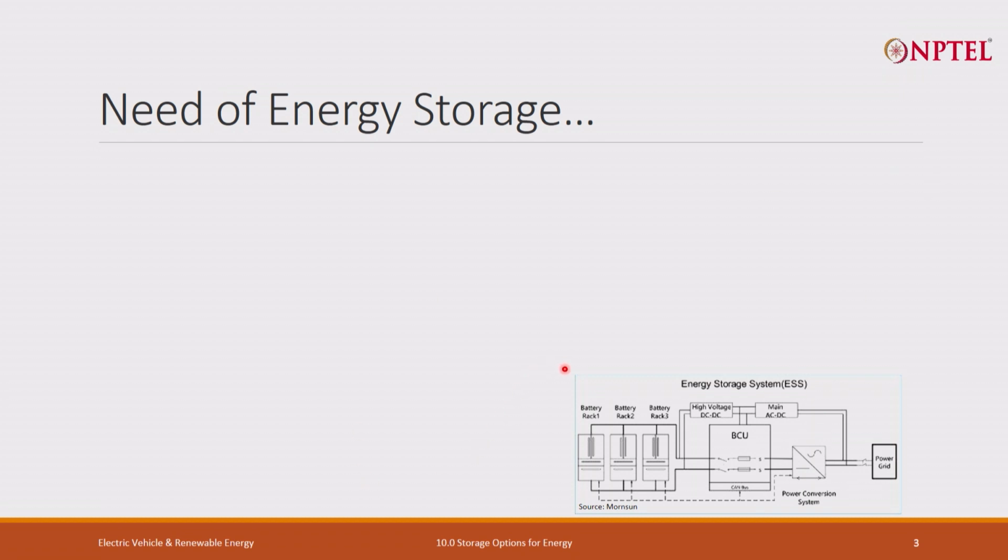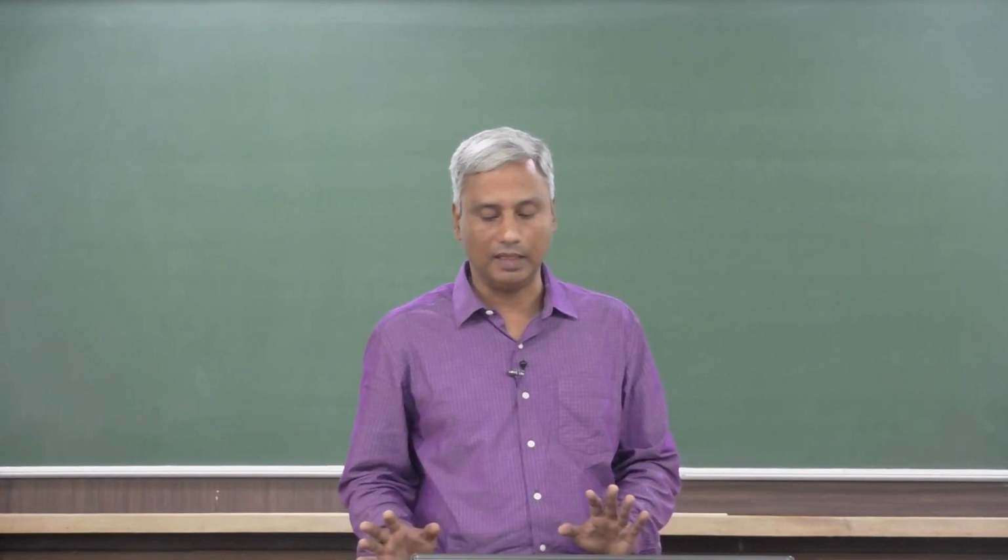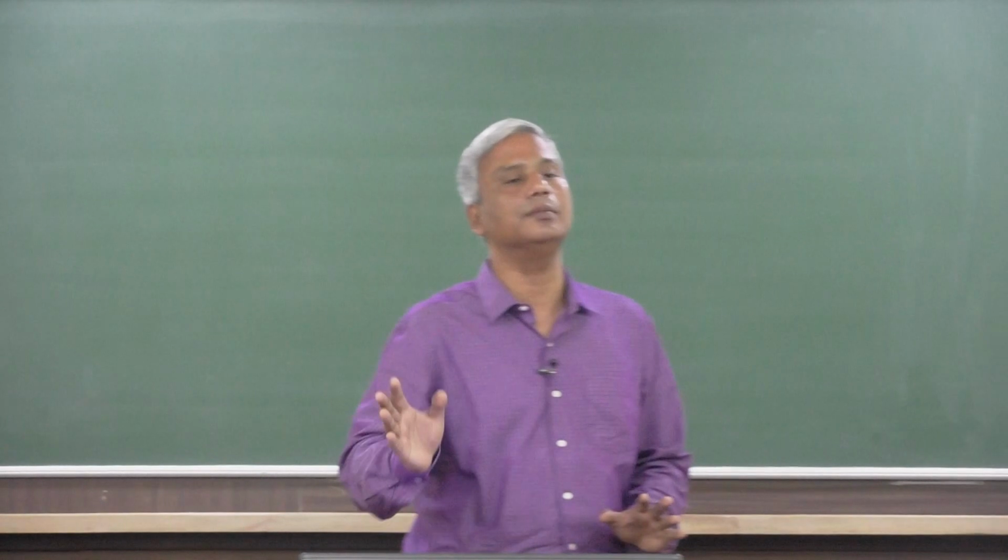So all of this together up to here, we say it's an energy storage system, because as per the definition we gave, it can store energy in usable form and give it back in usable form. A battery simply cannot give you the energy in usable form. So what we require is a power conversion system. We also say it's a power conditioning system. And then you also need a control, for when it needs to be switched on, when it needs to be switched off, what the storage rate should be, meaning the capacity rate, at what rate you should discharge it. All those things you need to take care of, and that's what we call power conditioning. And then next comes the energy management system.